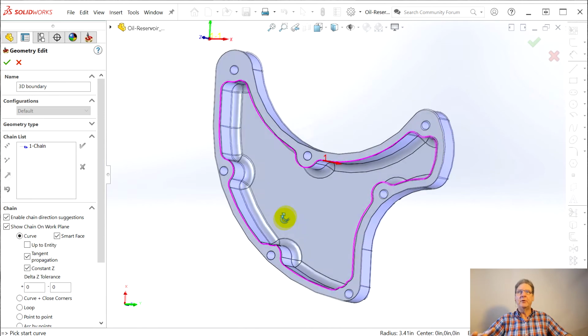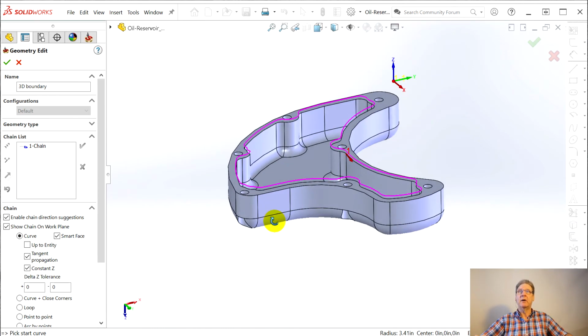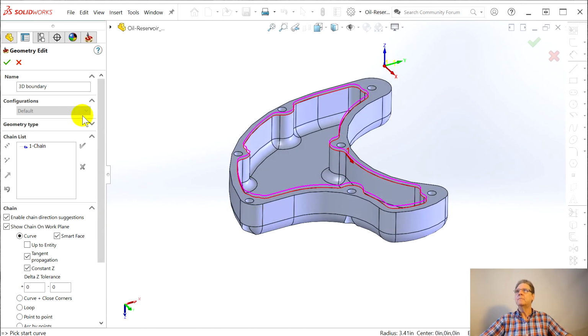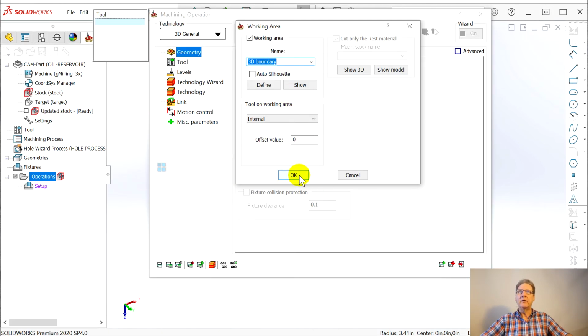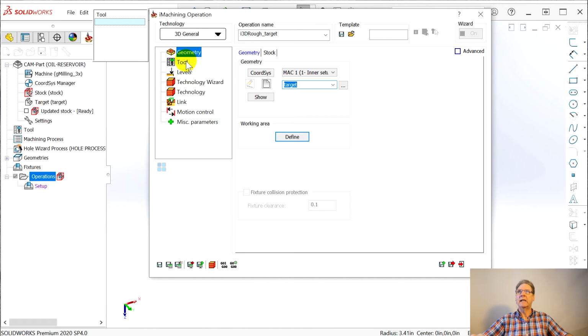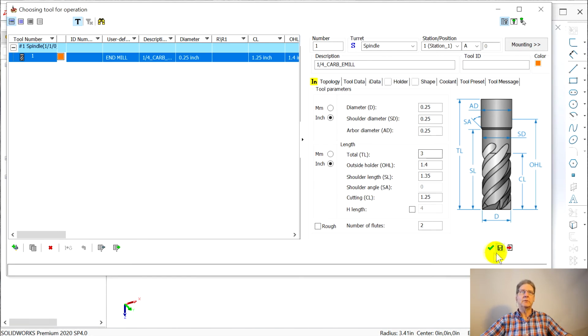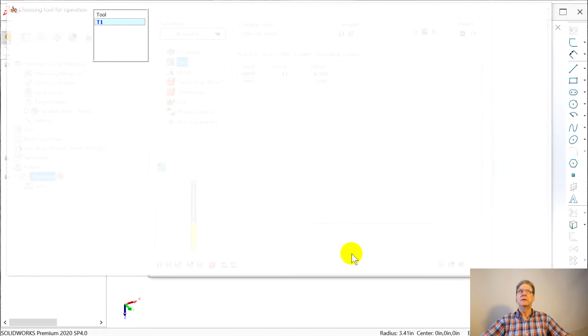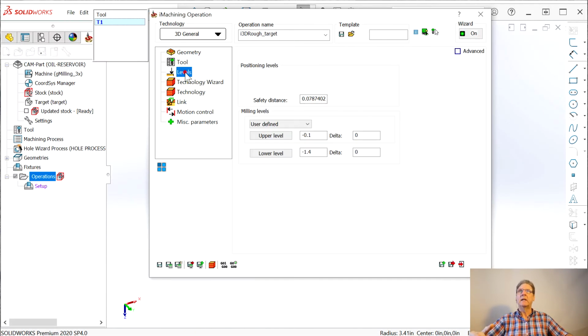And if doing 2D, it's kind of a pain. You got to use that up and down and go and get this curve, go down, over, back up in these two places. With 3D iMachining, it's smart enough to do that. So we say, okay, we like that 3D boundary. We say, okay, we've done our boundary work. We've got inside tool. Once again, it's different than the other dialogues. We've got our end mill. Say, okay, because I did this already 3 times.